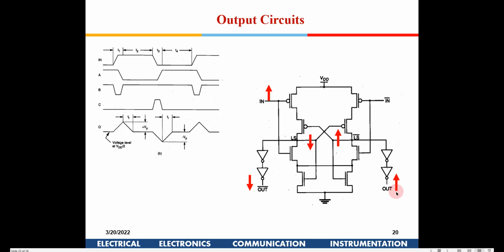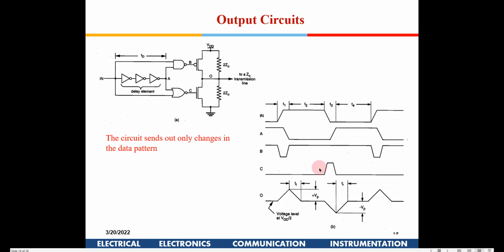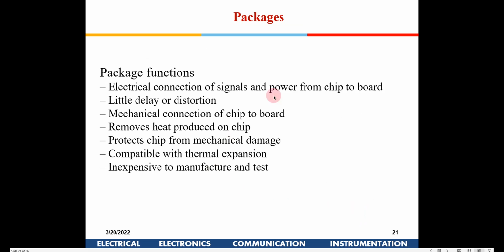proper digital output. Okay, so by using this circuit, the advantage is that there is no large power consumed here, and there is no drop in voltage in the bonding wires and all, because there will be a lot of parasitics in the chip bonding and things, and in the bus lines which connect one chip to another. So to prevent that, this is the kind of signal which we use. Instead of using a proper 1 and 0, we can use these kind of signals also. Okay, and then coming to the last part of this, which is packages.